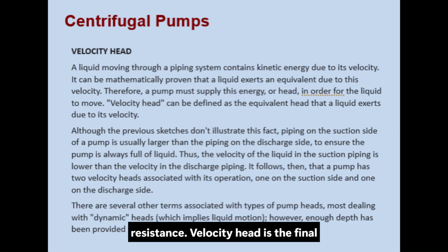Velocity head is the final head component we will discuss. A liquid moving through piping possesses kinetic energy due to its velocity, and this translates to an equivalent head that the pump must supply. It is worth noting that suction piping is typically larger than discharge piping, ensuring the pump remains full of liquid. This means the liquid velocity, and therefore the velocity head, differs between the suction and discharge sides. While there are additional head-related terms in pump engineering, we have covered the essential concepts for this introductory level.